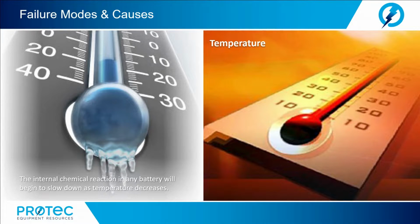All right, now let's take a look at temperature. The internal chemical reaction in any battery will begin to slow down as temperature decreases. The degrees of reduced performance will vary according to the battery technology. For example, at temperatures nearing freezing, a valve-regulated lead-acid may need capacity compensation of 20%. Lead-calcium cells using 1.215 specific gravity will require a doubling of capacity, while a NiCad will need about 18% increased capacity.